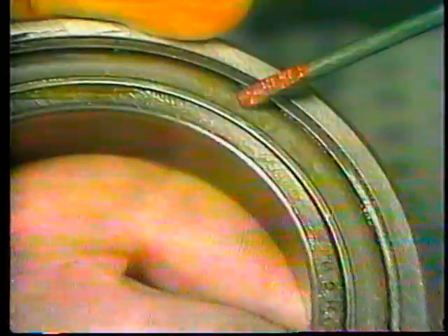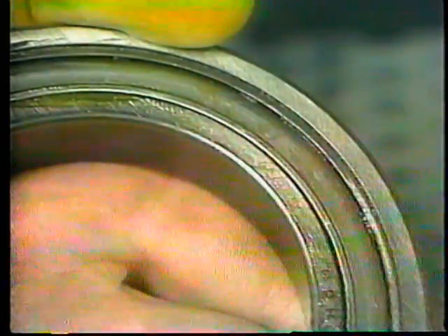So before you begin, look closely at the equipment to see if there is anywhere that the old grease can come out. In some installations, a vent plug is provided. In many cases, grease can vent without damage. There may be nothing more than a simple shield plate to protect components from dirt. Grease can push by it easily, and there is no danger of building up grease pressure inside the component.